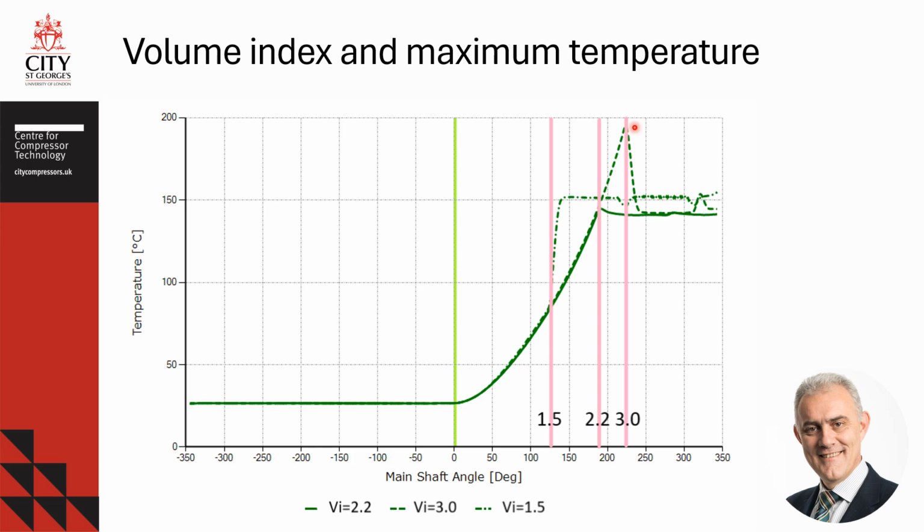One would think that increasing clearances would solve the problem. It will not. The compressor with higher clearances will have higher volumetric losses, lower efficiency, and it will lead to an increase in temperature. Such a compressor will obviously be less efficient and still experience even higher temperatures and still have a risk of rotor and casing contact.